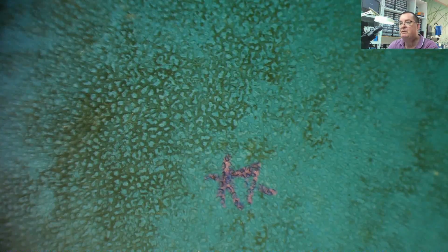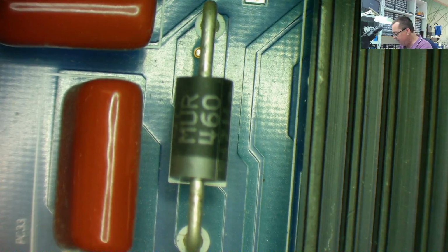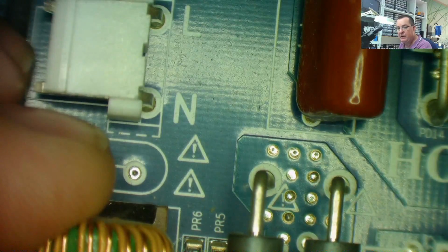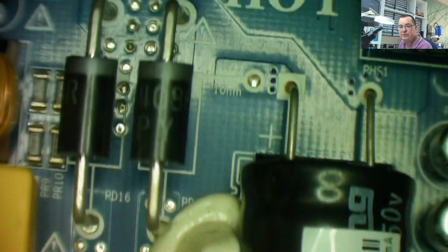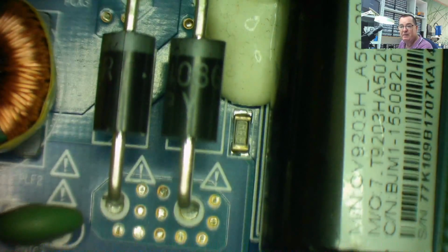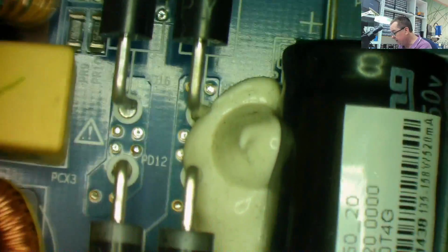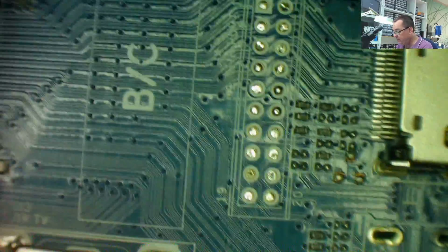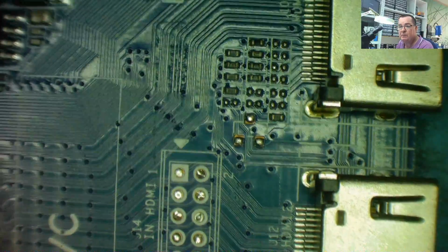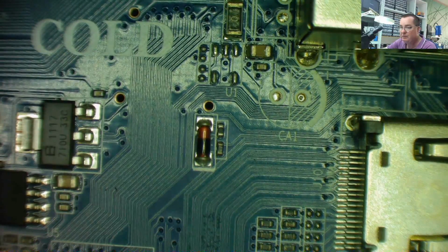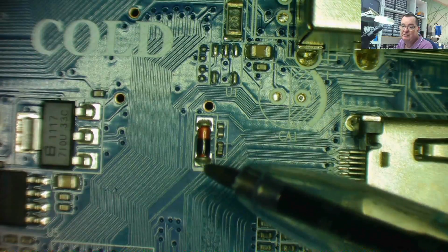Now let's have a look at some surface mount diodes. This is a power supply from a TV. These are through hole, but you can see diodes on here. These four together are actually a bridge rectifier made up of 4 discrete diodes rather than an encapsulated device. Over here, if I can just find it, there is a surface mount diode, that thing there that I've just built into the middle of the shot. So this is a surface mount diode. Again, the black is generally the cathode.